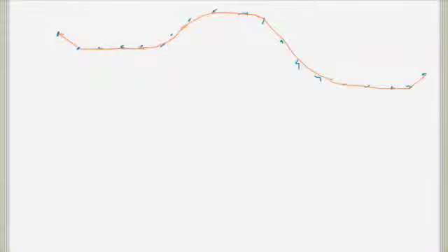And then, say if I'm doing your FET, you'll have your channel region, other discontinuity going either up or down. So if I draw that all together, you invariably get something weird happening right at that last node or a couple of last nodes, like that, due to fixing the potential at the end. Because the self-consistent calculation never quite matches up with the perfect ideal lead that you use to approximate this potential in the first place.